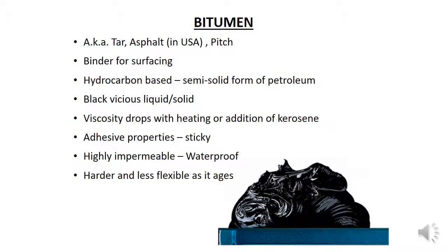When it is heated, bitumen also becomes very sticky and will adhere to most substances. This means the bitumen is able to provide a strong bond between the base course, or previous road surfacing, and the aggregate. This strong adhesion is essential if the traffic loads are to be transferred to the base course. Another feature of bitumen is that it is highly impermeable. That means that water cannot soak through even a thin layer of bitumen, which enables it to waterproof the road surface. It is also insoluble in water, so it is not prone to chemical breakdown by contact with water.